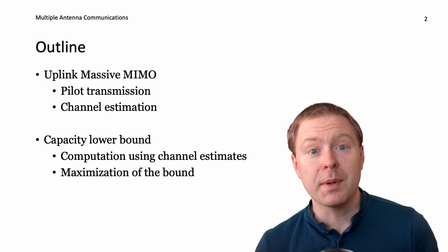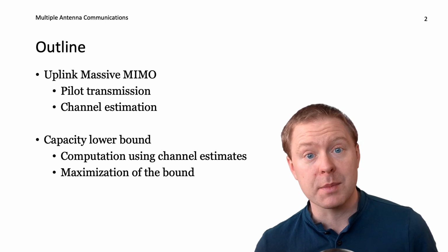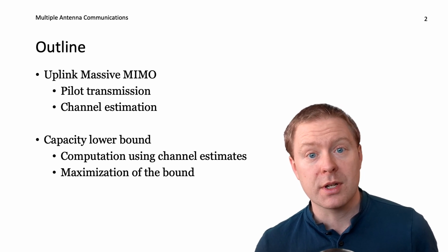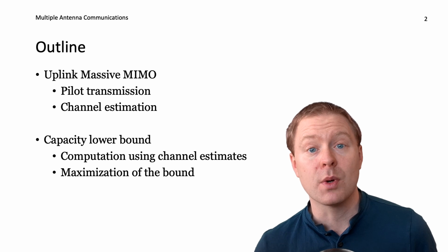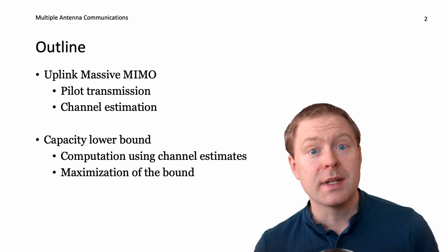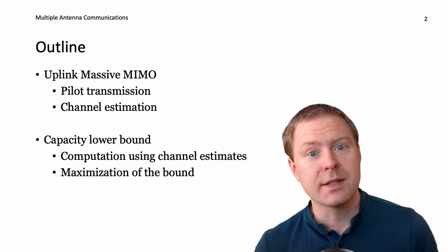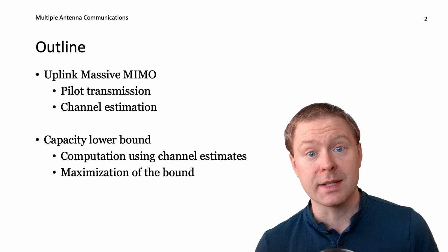This video is about the uplink of multi-user MIMO or massive MIMO systems, where multiple users are sending data and pilots to a base station. And we start with how the pilot signals are utilized in order to estimate the channels, and then how the base station is using those estimates to decode uplink data.